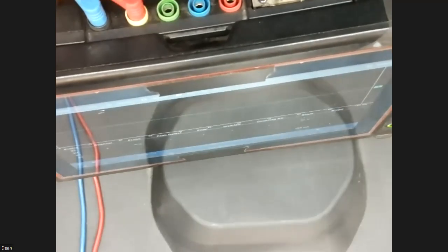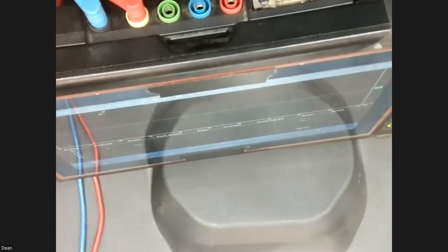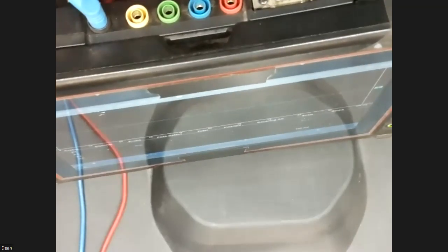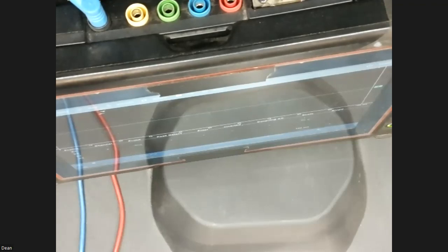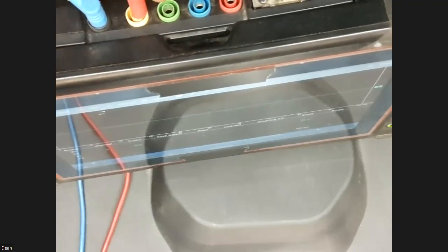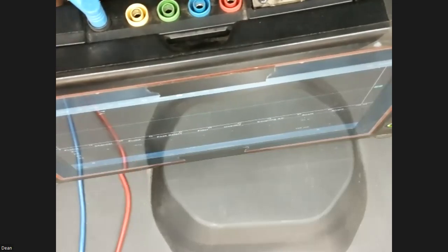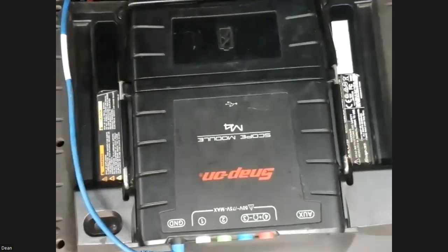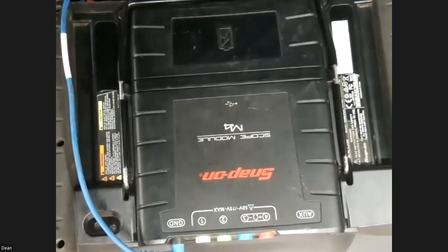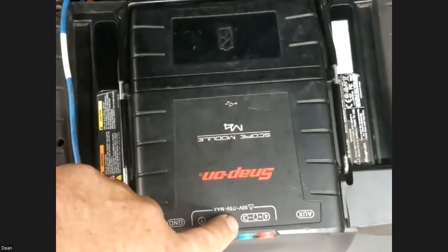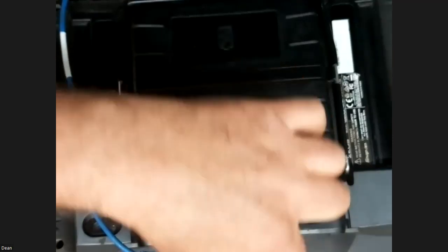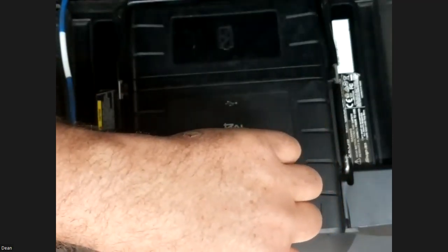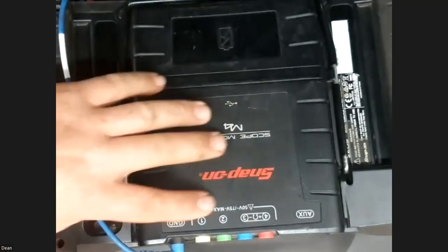But there are 4 scope leads on these today. And it doesn't matter if I'm using a voltage lead in one or the other. I could use this, or I can grab my amp clamp, and I can hook my amp clamp up to channel 2 or channel 1 or channel 4 or channel 3. It doesn't really matter. The only time it matters, most scopes will tell you, is if it says right here, resistance. So if you're going to be checking resistance in the circuit, you need to know that 2, 3, and 4 are going to need to be hooked up together. You can check resistance in the system.